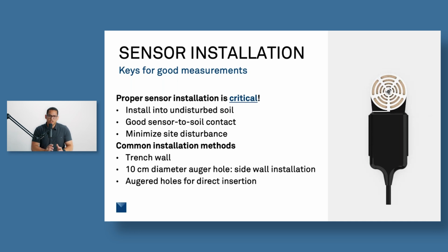We won't hit too much on that because it's not my preferred method, if I can avoid it. One of the reasons is that it typically means more site disturbance, because you have to dig a big enough trench that you can get into the depth you want to get to, and you have to get in there and actually install the sensors by hand.